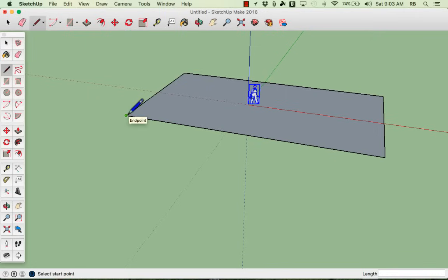Okay, great. Now, I could go ahead and attempt to create the walls of this house. That would be the next step probably, right? And I could click here at the corner of the house and I could try to create a wall vertically. And it looks like it's working fine. The line is coming in blue, as you can see, which is a good hint that it's on that blue axis. And, you know, I could probably successfully do this and create a wall. But more often than not, you may run into some trouble, especially if you're new at using SketchUp. And so for that reason, I'm going to want to undo what I just did. I'm just going to do Edit, Undo, Draw Line, or Command Z or Control Z to get back to where I was before.